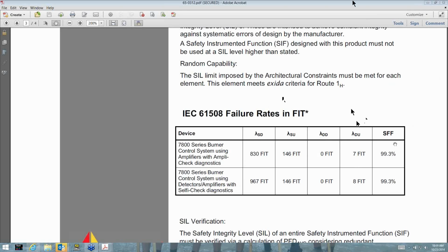The thing to measure here is, we talked about cost being critical in safety, but just because you have a high price doesn't mean you have a highly reliable device. This device that we manufacture sells for $800. If you compare that against other transmitters in the market for safety instrumented systems, this really helps you build a system, say 2 out of 3, or voting logic that's reasonably acceptable or cost effective. But let's not forget diversity. Common mode failure is a critical issue. So if you're using other manufacturers' transmitters and you're going 2 out of 3 or 1 out of 2, make sure that diversity is in there.